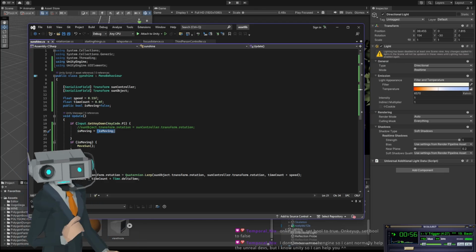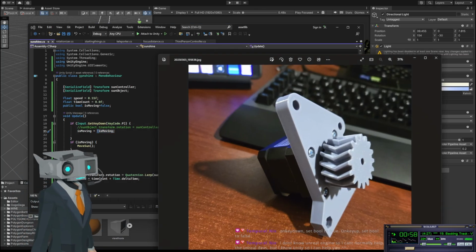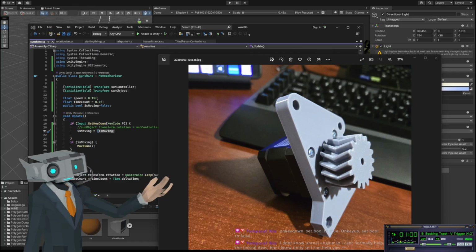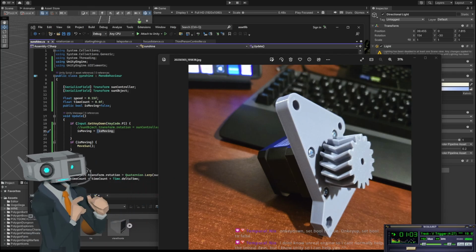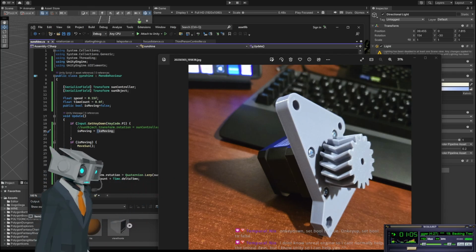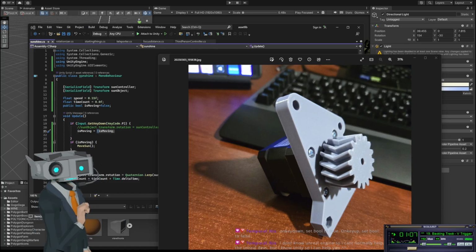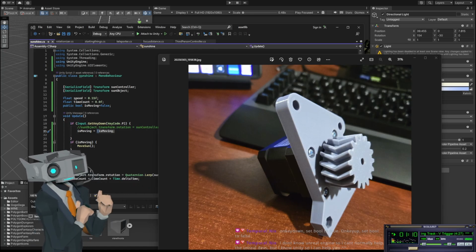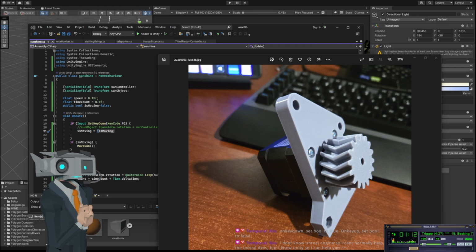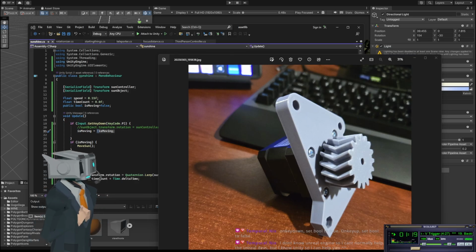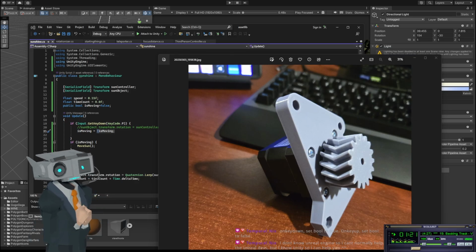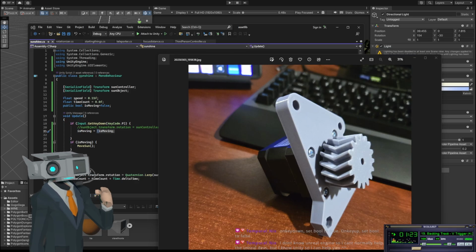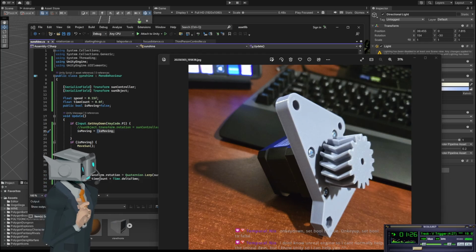But Nix, before you got in here, we're working on the upgrades. I don't think I've posted this in the Discord yet. But yes, this will be Rusty's new neck motor. We're switching from a servo to a stepper, which means I had to put a whole new way of doing things on there. But it definitely has a lot more torque than the servo motor we're currently using in the neck. Weighs a lot more and heats up more too.